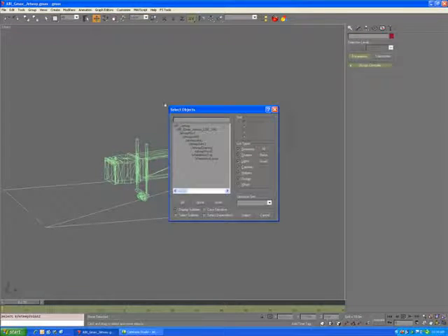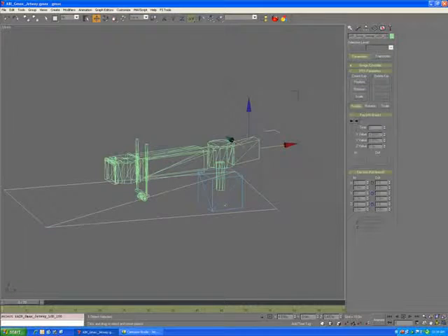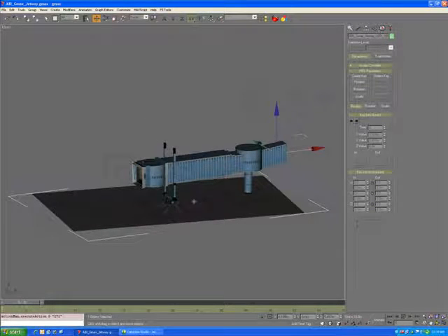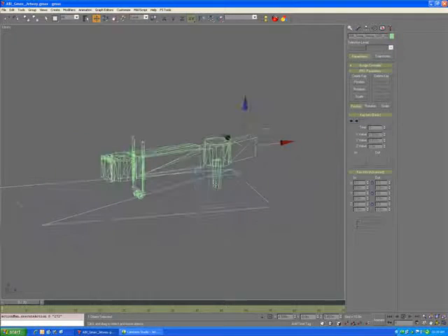And if you look at the hierarchy, you see there's 100 LOD, and then all of the pieces are linked to that 100 LOD. In this case, the 100 LOD is the staining that goes down on the ground to create the sort of parking space. The reason I have them as discrete pieces right now is that I will use these to create and align the bones and the bone structure, and then I will merge it all into a single piece and make it a single skinned object so that it takes one draw call to render.